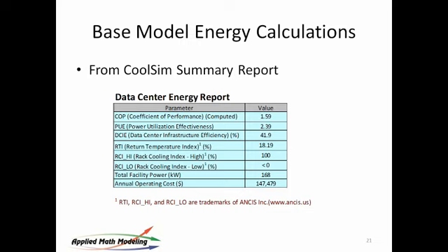You pick a point, you make some measurements, you validate the model, and then you modify that model to see how you can improve it. And hopefully those improvements will scale with the fluctuations of the data center. Exactly right. So it doesn't necessarily matter what the COP is to begin with. When I was in the Energy Practitioners course by the DOE, their methodology, Liz, was if it's a DX unit, the COP is 3. If it's a chilled water unit, it's 4. Because at the end of the day, what they were looking for is percentage improvement.